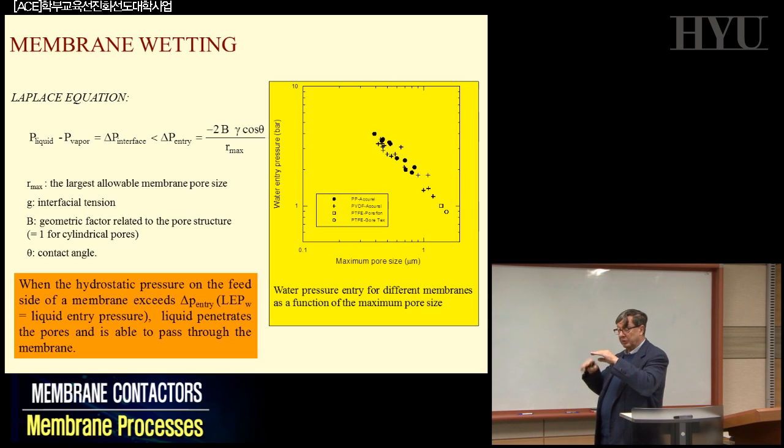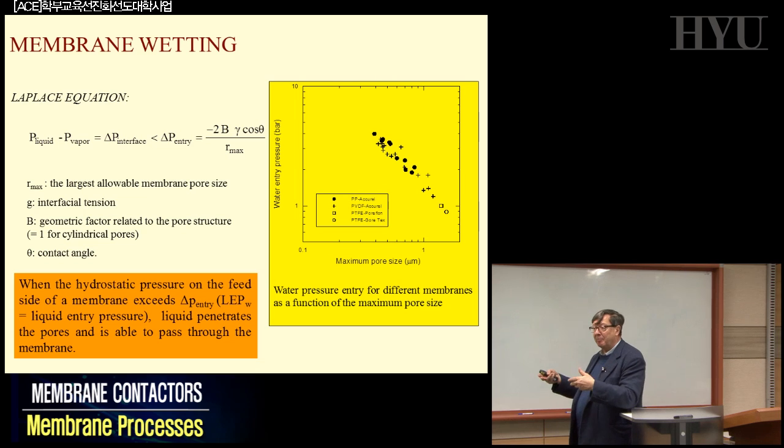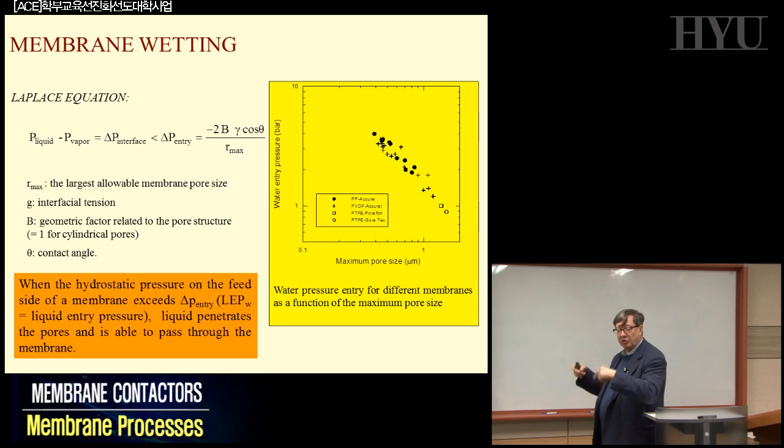And these membranes are the right one. Obviously, you also have to find a compromise here. Normally, that's why we were mentioning before, the ideal value is around 0.1, 0.2, 0.3. This is the range in which we like to have our membranes porosity. Because in this case, we have an order of magnitude of the LEP of the order of 5, 6, 7 atmosphere, and so there is no problem of any liquid penetration if you don't apply 7 atmosphere. But normally it does not happen that you create 7 atmosphere by pressure drop, etc. Okay? So that is important.